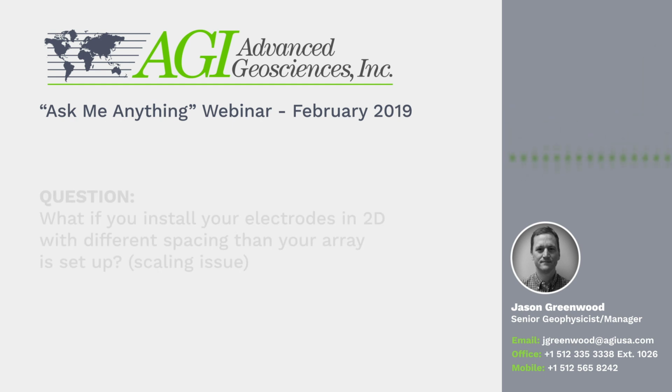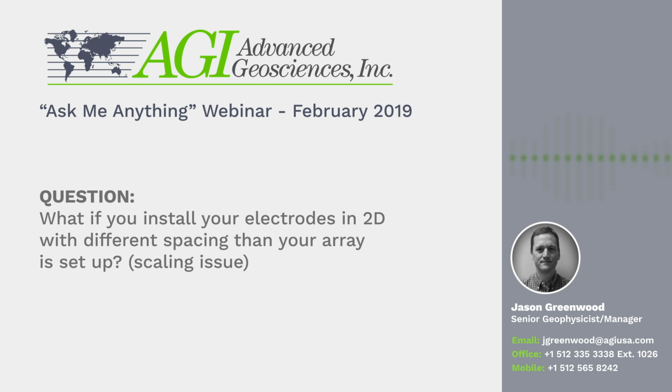Okay. First question is just a little bit of a field issue, I would say. When you're collecting 2D lines with the SuperSting, there can be one command file for any measurement settings and any electrode spacing which your cable is capable of doing. So let's say you have 56 electrodes with a maximum of 6 meter spacing, or about 20 feet. And your particular project needs to deploy at 2 meters.